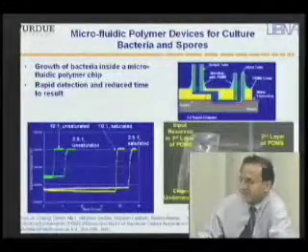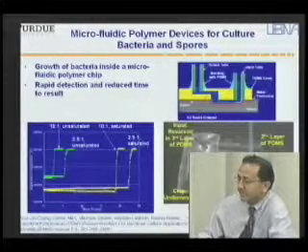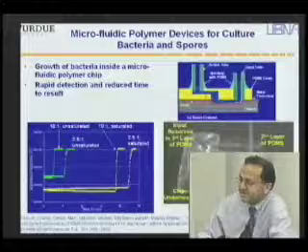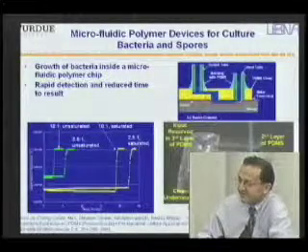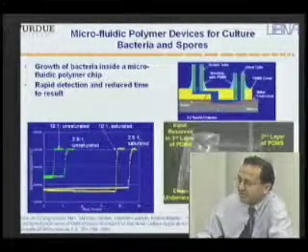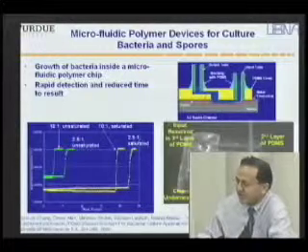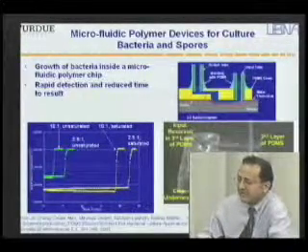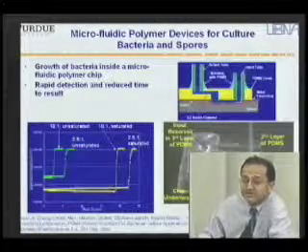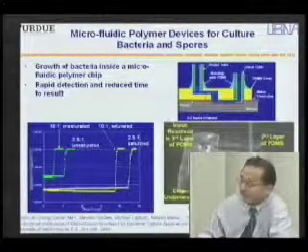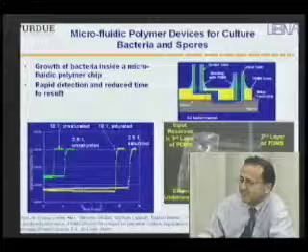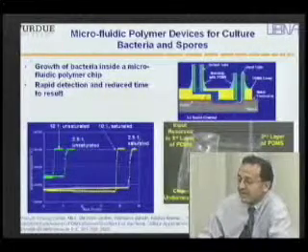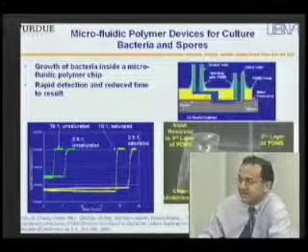One of the issues with PDMS is the fact that it is a porous material and fluid can actually evaporate through it. So if you have very small channels or very small chambers and you want to keep that fluid and use it over a long period of time, then that's always challenging. So there's some results here where you can use different materials by changing the composition of the PDMS and making it stiffer, and then you can increase that evaporation time of the fluid from a few hours up to 20 hours or so.